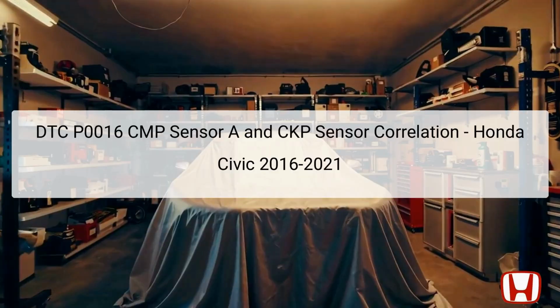DTC P0016 refers to the CMP sensor A and CKP sensor correlation issue in Honda Civics, manufactured between 2016 and 2021. This error indicates a correlation problem between the camshaft position, CMP, sensor A, and the crankshaft position, CKP, sensor. These sensors are crucial for the engine management system as they help determine the engine's timing for optimal performance.